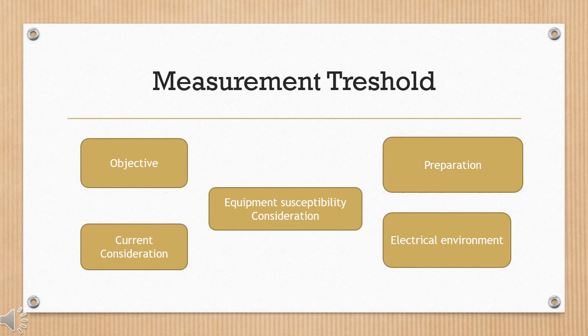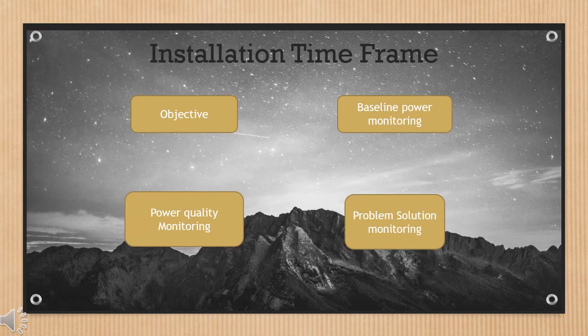So the proper setting of the threshold determines whether the data gathered are useful data to keep. A threshold set too low results in irrelevant data, and a threshold set too high results in insufficient data. So we go to the last part, which is the installation time frame.